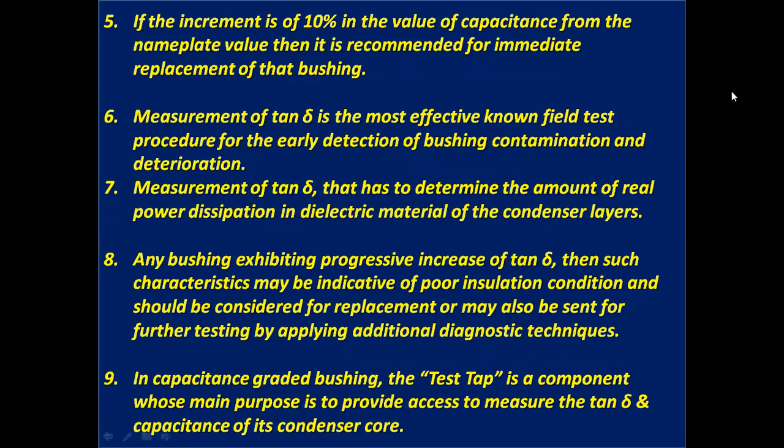If the increment is 5% from the nameplate value of capacitance, then further checking should be needed. And if the value is more than 10%, then it is recommended for immediate replacement of that bushing.